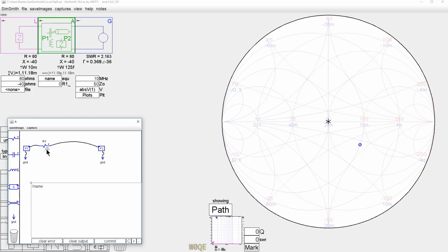And what I'm going to do with this resistor, I'm not going to give it a value, so it's going to force us to give it a value up here. Let's say call it 10 ohms for the moment. If we take this circuit right here and we put a label, so right there, give it a name other than ground, which is a short circuit. Call it V1.